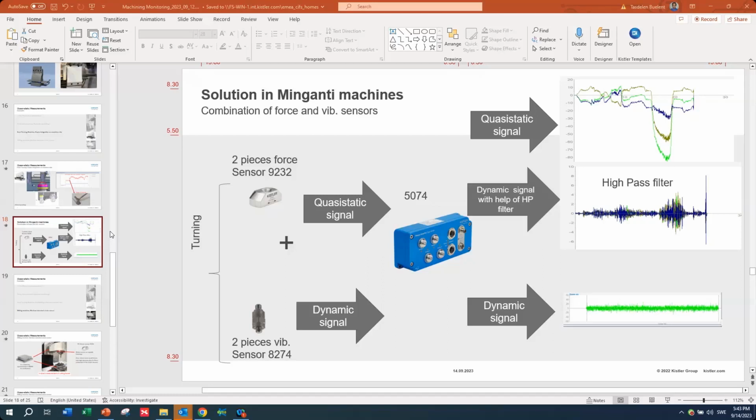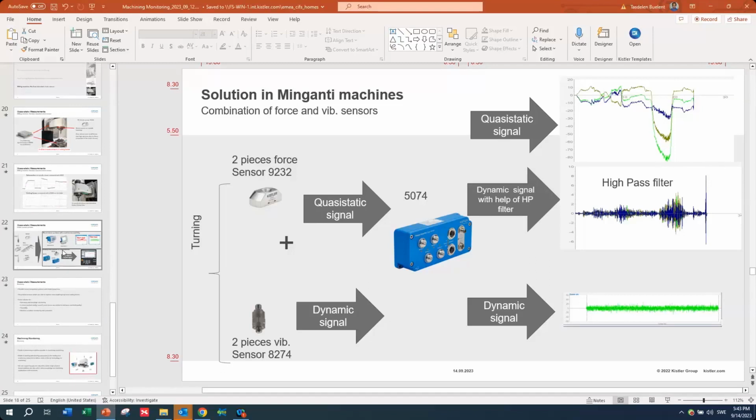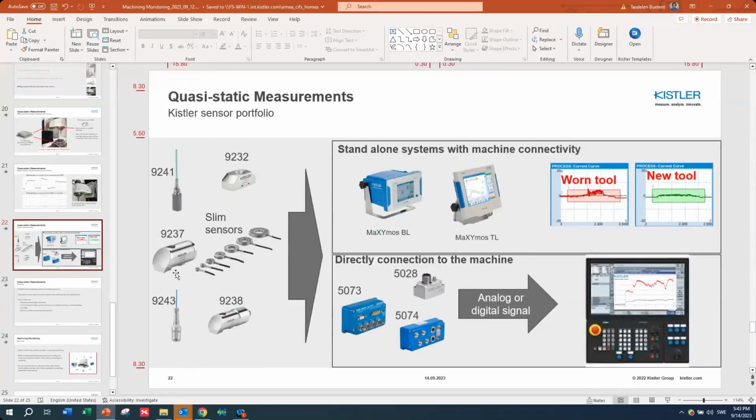But if you are talking about the solutions that we are discussing here, mainly our one-axis piezo strain sensors, it is not affecting it. Of course you are making small holes, but the change is not in the static stiffness, and the dynamic stiffness part is, as far as we have measured, negligible and it will not affect you. But of course it depends on where you are adding that sensor, right? And that is our know-how coming into the picture.